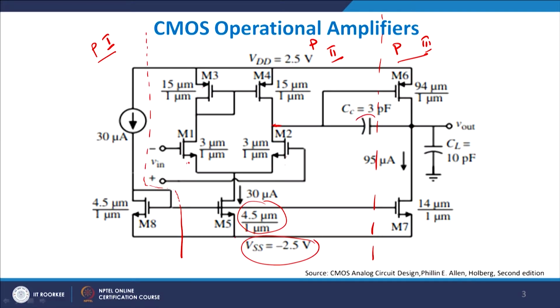Now, you do have a capacitor here, which is basically a blocking capacitor, because it does not let any DC component pass through it and reach this particular point. It only lets the AC component pass through it, because you do not want any DC component to load your subsequent stage. The subsequent stage now is basically your P3. We have finished with P2. So, this M3 was mirroring with M4, and the current was going through this point. As a result, the same current multiplied by RD is the voltage that appears across the PMOS here.